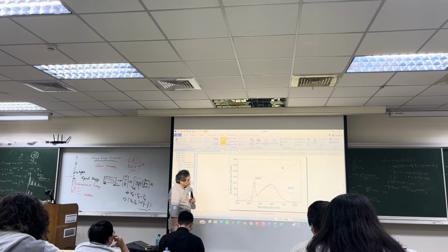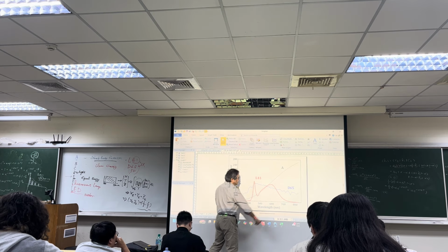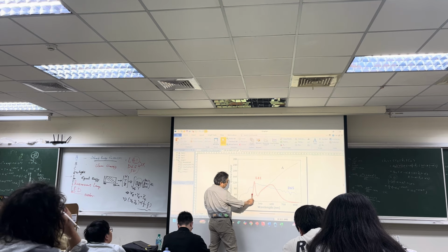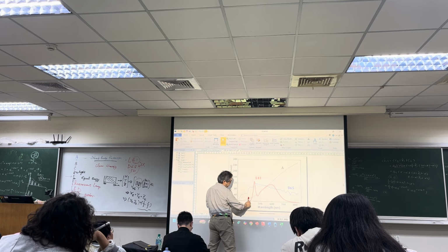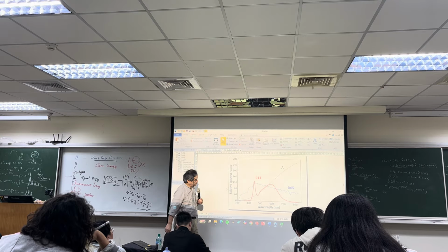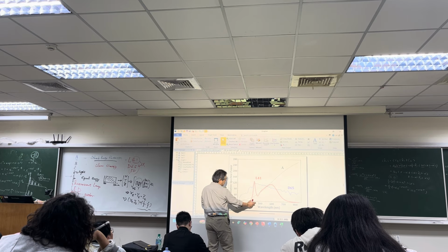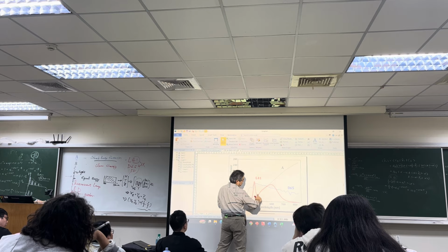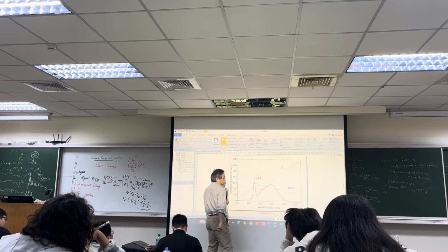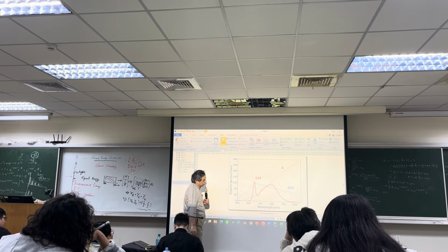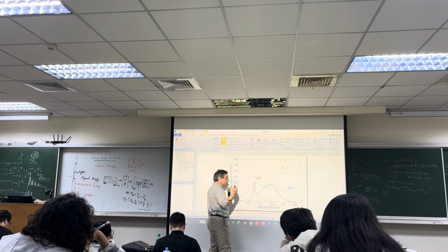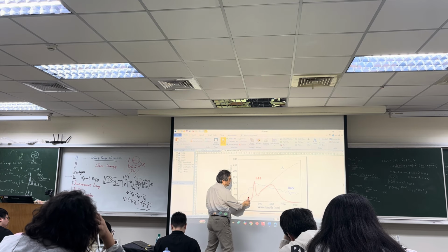So with this kind of spectrum, you can have a very clear idea. This spike, this peak, comes from the blue LED, and some part of the blue LED energy is absorbed by phosphor, which emits phosphor light. It is a kind of fluorescence light. Okay, so we have blue and yellow, so the spectrum looks like a white color.